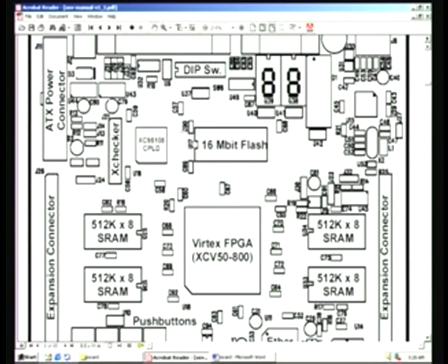In addition to this CPLD, we also have two-digit seven-segment LEDs, which we have already seen, and we will see a little later some details of how you go about connecting the different segments. In addition to this, we mentioned that there is a 10-bar segment, that is what is here. In fact, similar segments will be placed here, one below another, all 10 will be available here. This is a bar display, and you can use it for displaying histograms in some of the engineering units you may design, and you can use it for such applications.